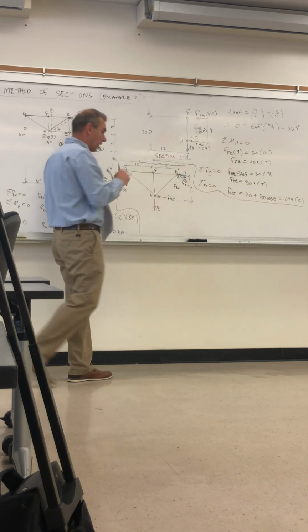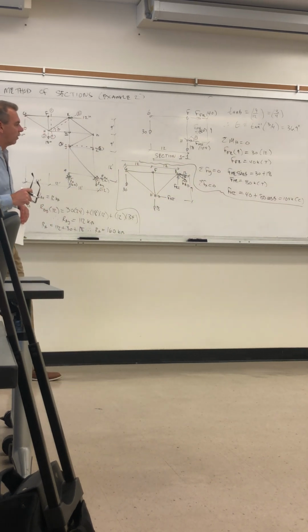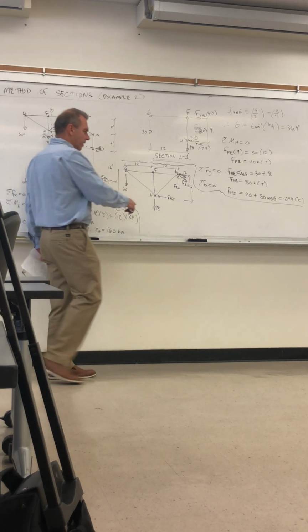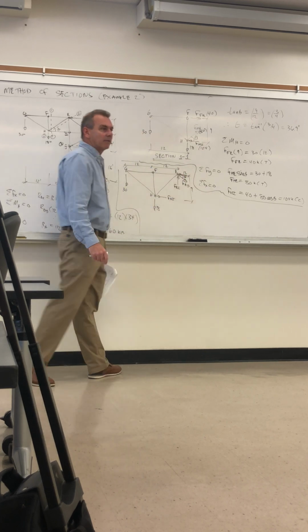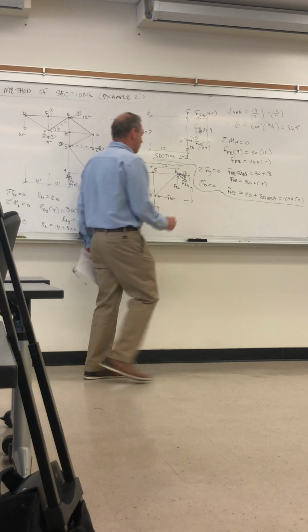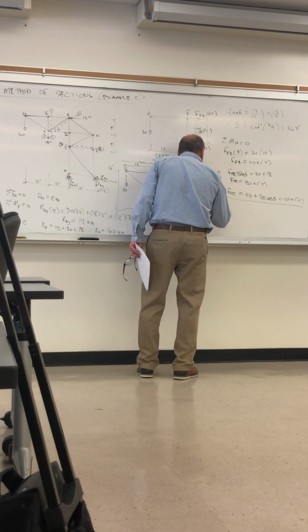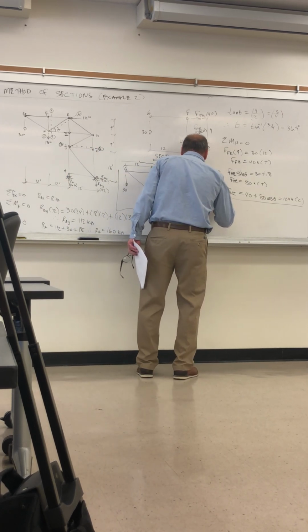So you see a lot of forces collected going right through E. So we can say, in order to solve for F of HI, we'll do that first by just summing moments about E. That's the simplest, right? So we have summation of moments about E equals 0.